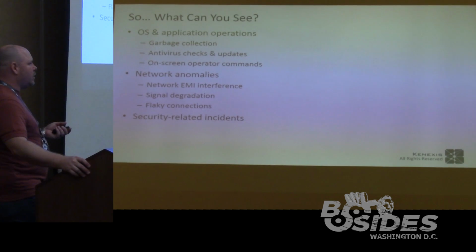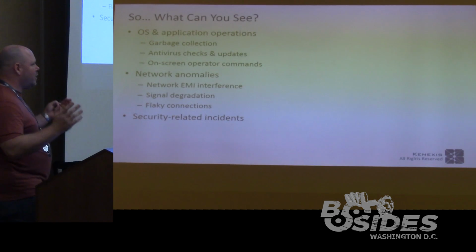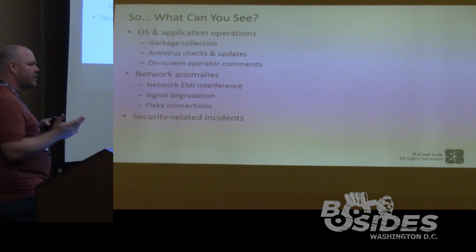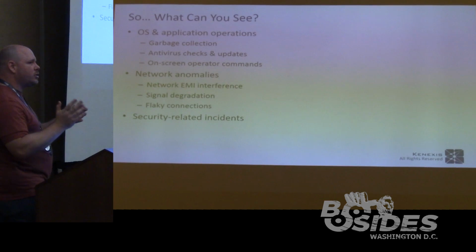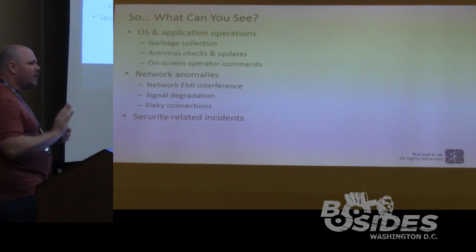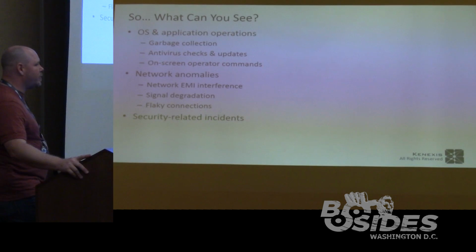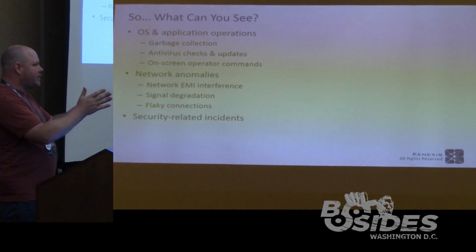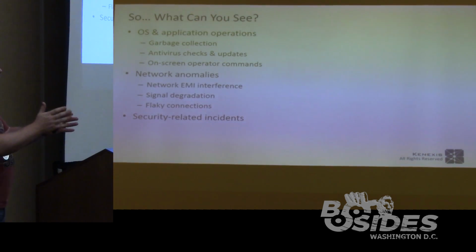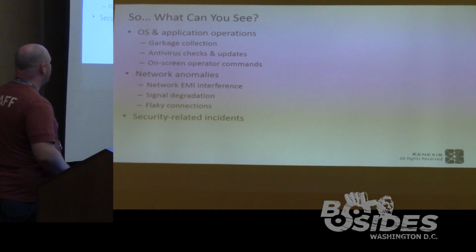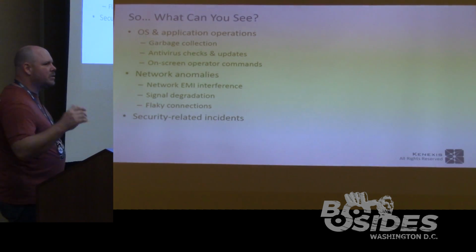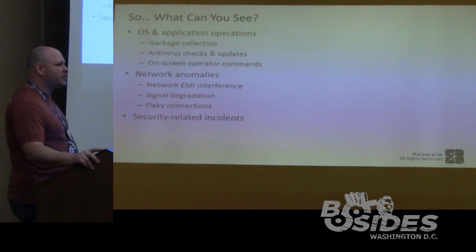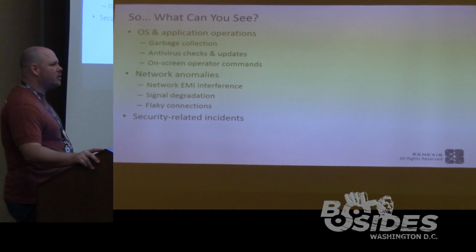Signal degradation: you're dealing with places where there's a lot of metal. Almost every machine is made of metal, and if you're dealing with wireless networking, there's a lot of refraction and a lot of reflections, and you'll end up with a real mess in some cases. So they have to be really careful. Literally, you could be here and get 10 reflections, and then be over here and be fine. So it happens a lot. Flaky connections, stupid human tricks with forklifts and dump trucks and people hauling stuff around. Anything that could go wrong with a network has happened in an industrial plant.